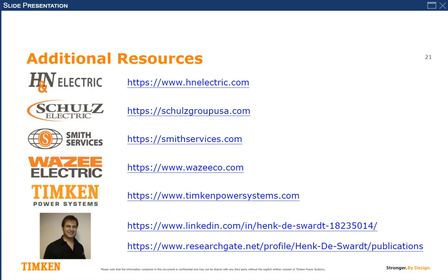Normally, another thing you need to look at on machines is greasing or lubrication. That's very, very important. On the nameplate, it should tell you what the regreasing interval or the oil life is. Do look at that. Do grease the bearings with the correct amount of grease and the correct time frame. We see often that people send around their routine maintenance staff and they grease every bearing they can find.